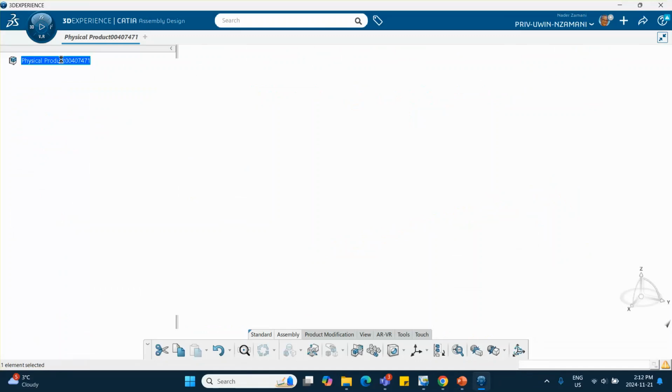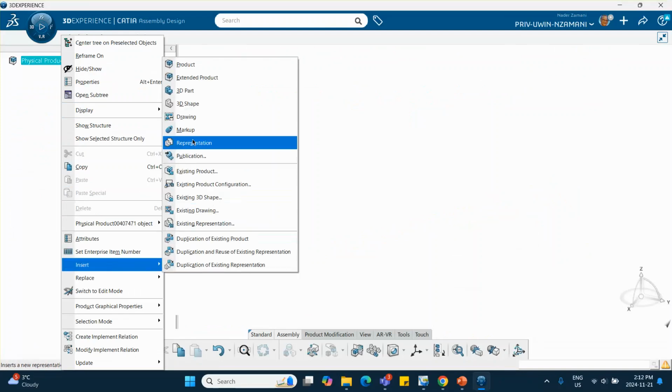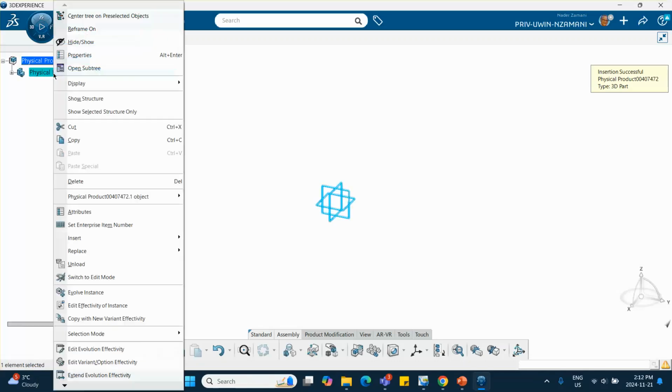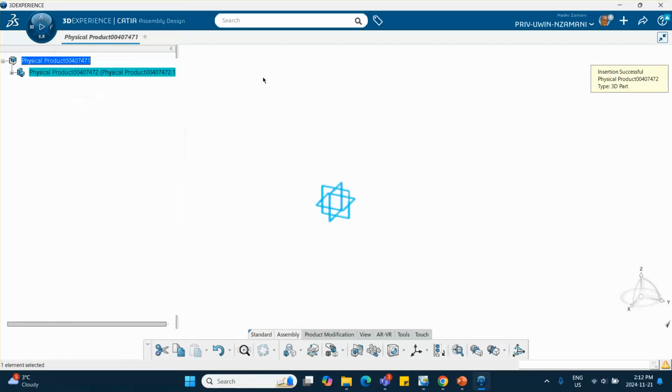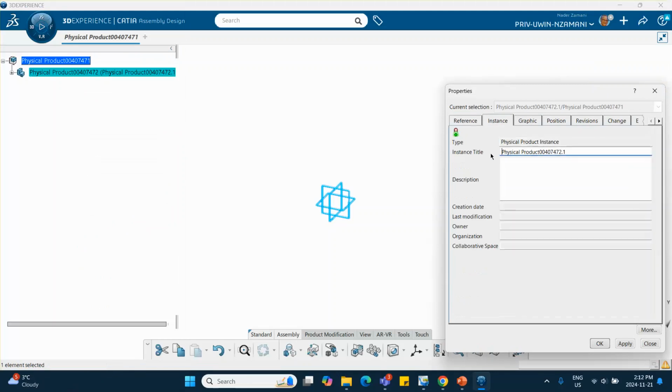First, I'll do the base. Right click, insert 3D part. I'll make a base which is about maybe 1 inch diameter. Okay, I'm going to rename this in properties so that it says base. That base is stationary, that really does nothing except for making a revolute joint there.